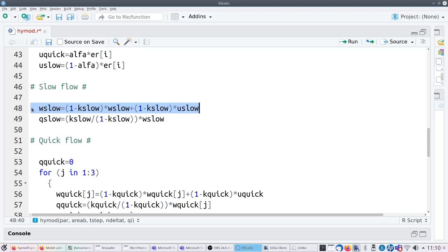So this way, which I selected to compute the storage into the reservoir, allows you to take into account at the same time inflow and outflow, which is in a way more precise, more correct with respect to the approximation that we used in the linear reservoir code. And I need to put a comment on this in the code on my website, to highlight that this is more precise, put a comment in linear reservoir, I take a note.